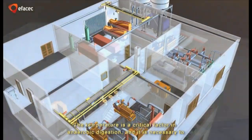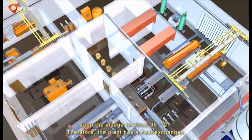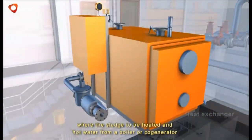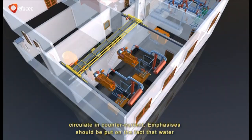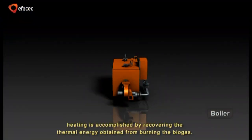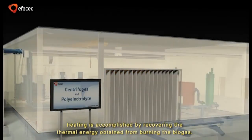The temperature is a critical factor in anaerobic digestion, and it is necessary to keep the sludge at about 35 degrees. Therefore, the plant has a heat exchanger where the sludge to be heated and hot water from a boiler or cogenerator circulate countercurrent. Emphasis should be put on the fact that water heating is accomplished by recovering the thermal energy obtained from burning the biogas.